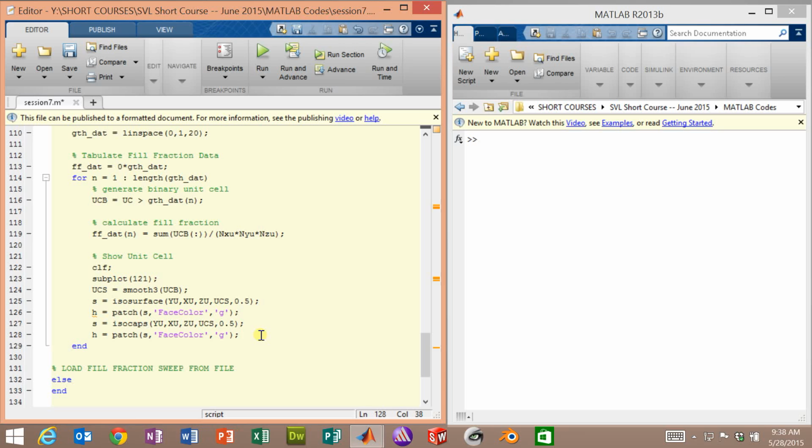And that'll draw the caps on the ends of our 3-dimensional device. We'll give it a view. We'll view it from an azimuth and elevation angle of both 10 degrees. We'll give it an axis equal tight. Remember, we always would like to look at our spatially variant lattices with equal proportioning. They're weird and crazy enough to look at without that. So we'll keep that here.